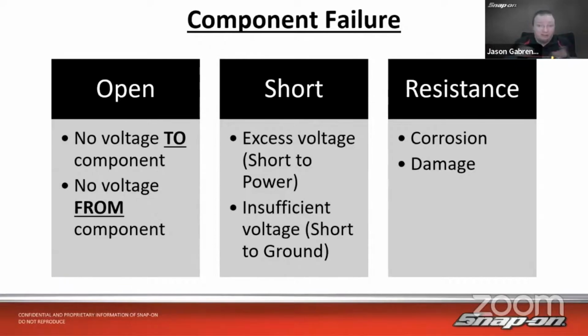And think about damage, right? Talked about that rubbing on the engine block. If I fray a wire, even if it's not shorting right now, that could cause a resistance issue. Think about a multi-strand wire, like maybe a battery cable, right? Lots of multi-strands. If I were to take my ohm meter and put it on either end of that multi-stranded battery cable, I'm probably going to get 0 ohms or pretty darn close, right?